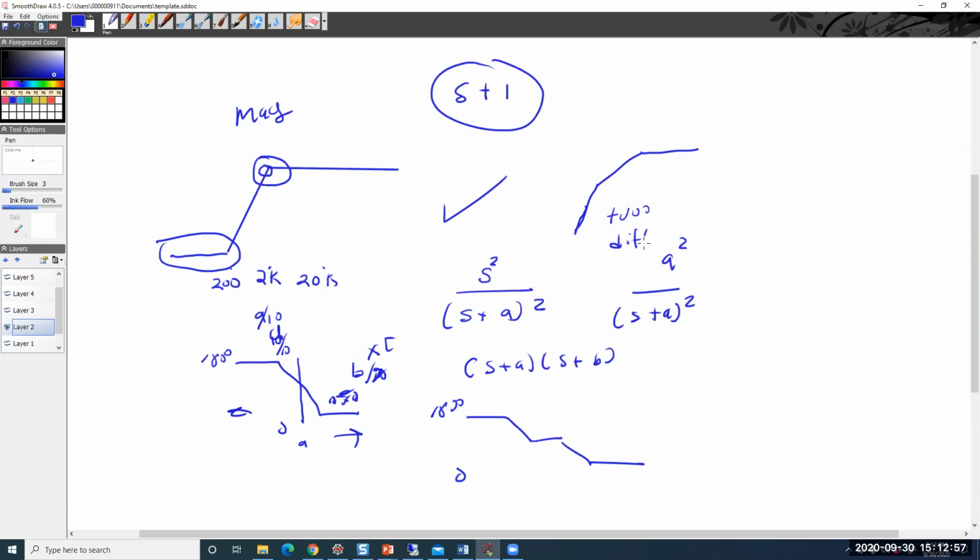And that's for 2 different poles. You could have this, and that's at 40, and that's where the pole is repeated. And the thing is that's plus 40, that's plus 20, and then the slope evens out.